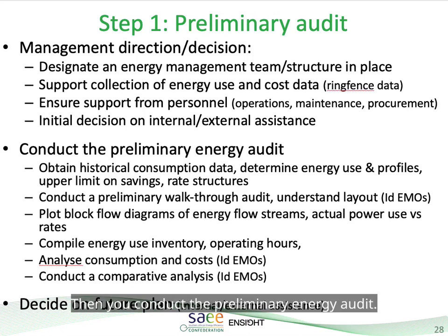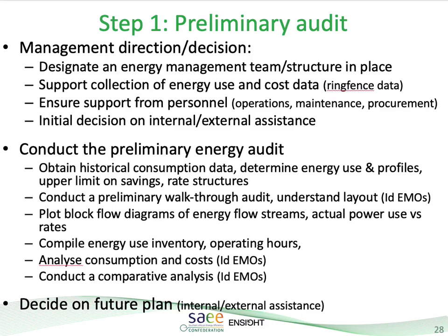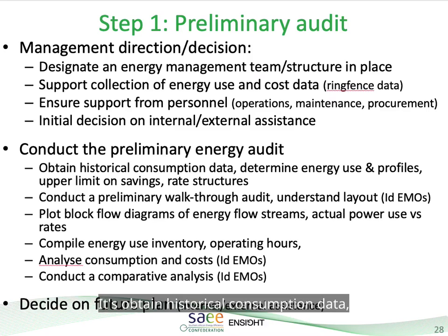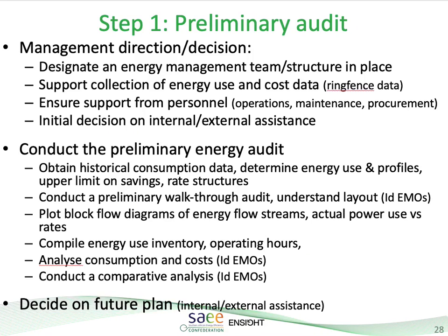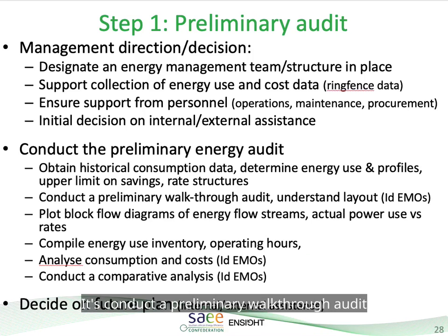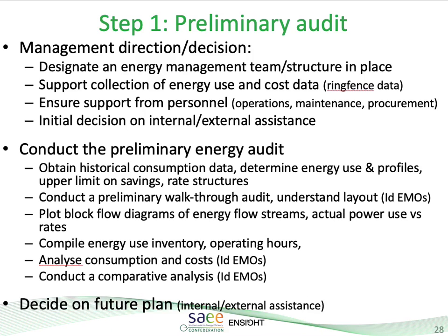Then you conduct the preliminary energy audit. It's to obtain the historical consumption data, determine energy use and profiles, upper limit on savings, rates, and structures. It's to conduct a preliminary walkthrough audit to understand the layout and the energy, in order to determine the energy management opportunities.